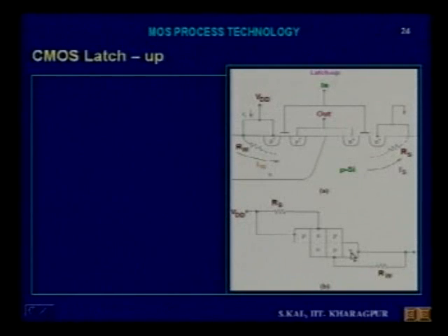And here one is the emitter, another is the collector, and at the same time you see this is a ground, and another resistance is also there. The resistance is the P substrate resistance. So this will basically be the RS, and this will be the RW. That has been interchanged. So now with this, you are getting a connection of the transistors in the form of some sort of thyristor action.